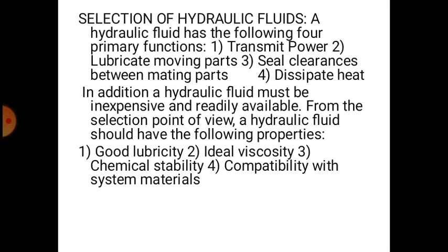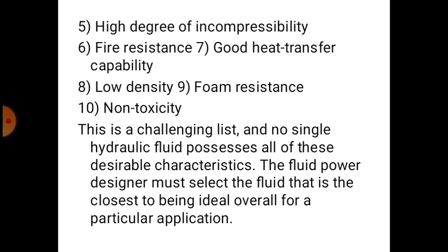From the selection point of view, a hydraulic fluid should have the following properties: good lubricity, ideal viscosity, chemical stability, compatibility with system materials, high degree of incompressibility, it must be fire resistant, good heat transfer capability, it must have low density, it must resist foam formation, it must be non-toxic.